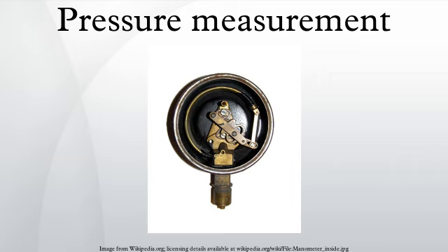Typical high-quality modern gauges provide an accuracy of plus or minus 2% of span, and a special high-precision gauge can be as accurate as 0.1% of full scale. In the following illustrations, the transparent cover face of the pictured combination pressure and vacuum gauge has been removed and the mechanism removed from the case. This particular gauge is a combination vacuum and pressure gauge used for automotive diagnosis.